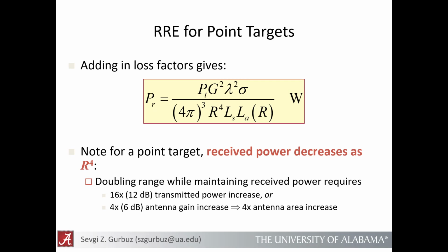So, for example, if you were curious whether one of the radars we had in our lab was going to be able to detect a drone at 1 kilometer, you would be able to use this equation to get an estimate for what your received power is. And usually for detectors, there's a rule of thumb that you want to have at least 10 to 13 dB of signal to noise ratio. And so with that information, you can do an initial feasibility analysis, for example, as to whether or not that would be an effective radar system for that particular application.